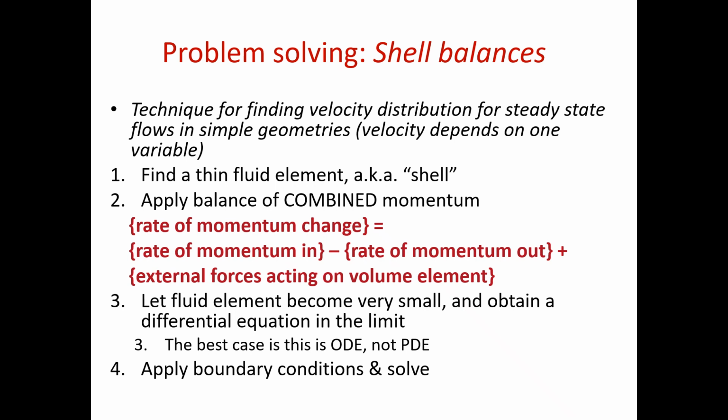So to actually look into what is coming into any volume, I'll have to sum up everything that is going across an area, either inside or outside, in the most general case. And stuff that is going inside is always stuff that is orthogonal to an area element. Now, if I have simple boxes, these things are relatively simple to put together, and that's what we're going to do in most of our cases. So we're going to simply look at our rate of momentum change or accumulation within that element as momentum that comes in minus momentum that comes out.